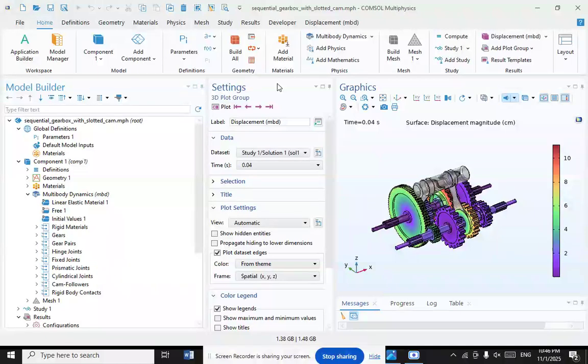In a vehicle with a manual transmission, the flywheel is attached to the engine's crankshaft, therefore rotating at engine speed. A clutch disc sits between the flywheel and the transmission pressure plate, which is attached to the transmission input shaft, controlling whether the transmission is connected to the engine or not. The clutch pedal controls the pressure plate. Clutch engaged: the clutch pedal is not being pressed and the transmission is connected to the engine. Clutch disengaged: the pedal is being pressed down.